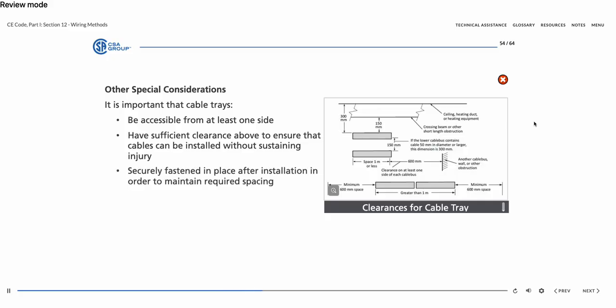With modular assemblies such as natural gas compressor stations and gas plants, customers may want a cable and cable tray wiring method. However, because of the clearance requirements in Rule 12-2200, it is difficult if not impossible to maintain those clearances. However, Sub-Rule 7 allows cables to have reduced clearances through chases, under gratings, and process pipes.